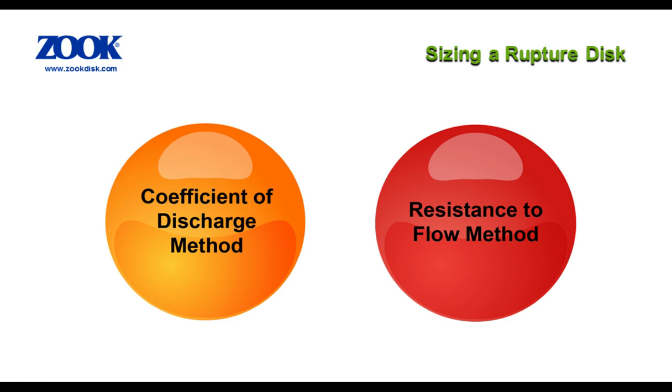A rupture disk or pressure relief valve manufacturer may opt to test a specific combination of designs to establish a certified CCF for that specific combination, which can be used in lieu of the default 0.9 factor. Typically, certified CCF values are higher than the default, but caution is recommended not to select too high a certified CCF value, as this can paint yourself into a corner if changes to either the rupture disk or PRV design are required in the future.